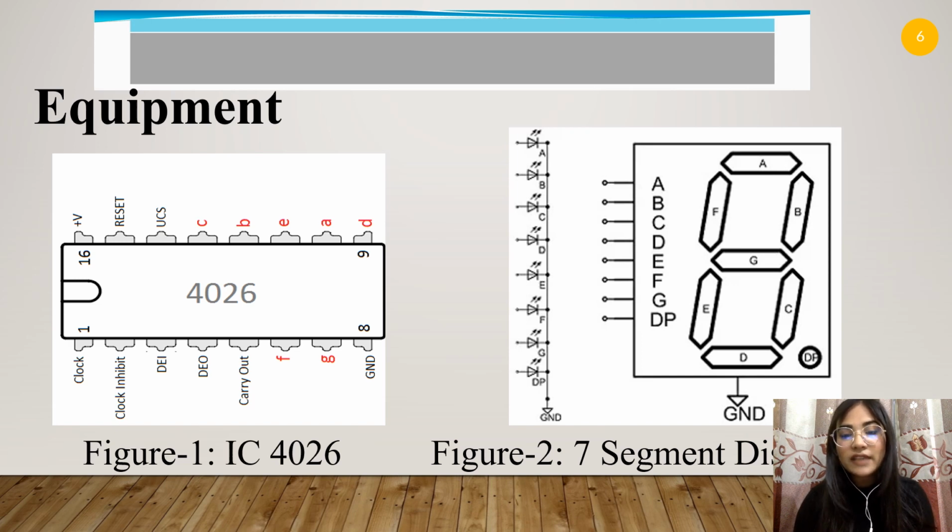The 7 segment display is common cathode, CC. In the common cathode display, all the cathode connections of the LED segments are joined together to logic 0 or ground. And how does it work? First of all, we put our multimeter's black lead on pin 3 or 8. Both are common pins as they are internally connected. Now put the meter's red lead on any other pin such as 1 or 5. If any of the display segments glow, then the display is common cathode.